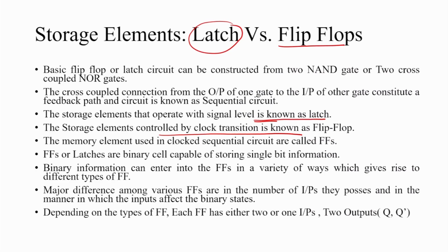Suppose this is a clock. What is the signal level? We can say that the latch is level triggered while flip flops are edge triggered. Simply, the latch is active only during this time duration, or the latch is active when the clock is low.